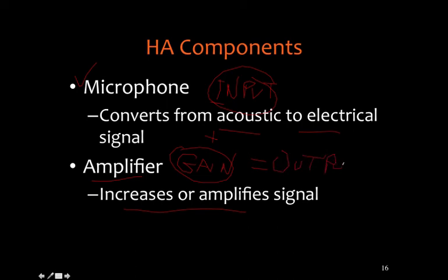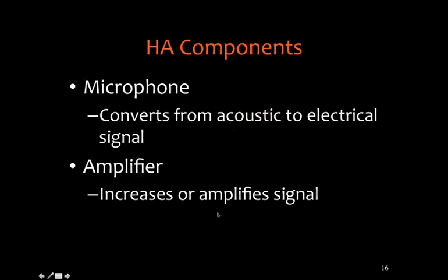We can measure this in specific electroacoustic test boxes, and we know what the input to the hearing aid is. So if I put a 60 decibel input into a hearing aid, and I measure the output, and the output is 90 decibels, then I know 90 minus 60, that means I had a gain of 30 decibels at that particular frequency, and so on. Those are all part of some standard quality control measures that would be employed on hearing aids.